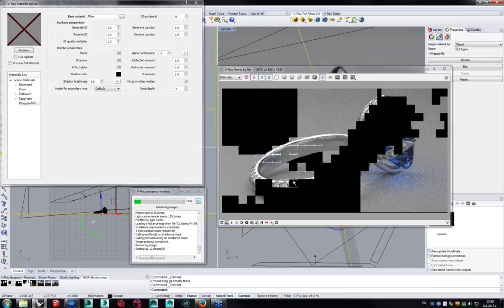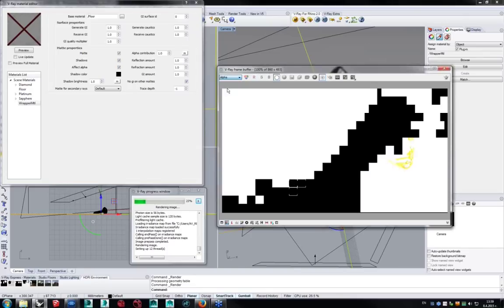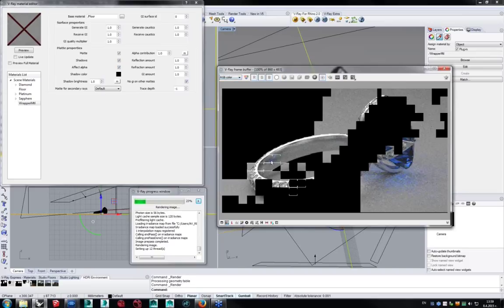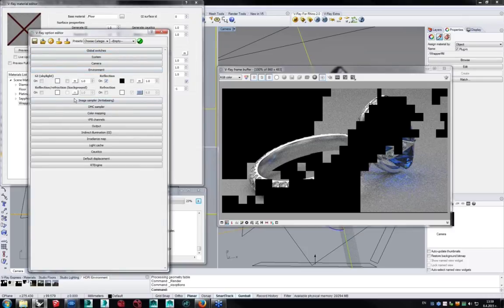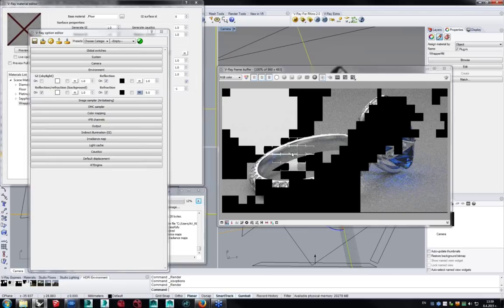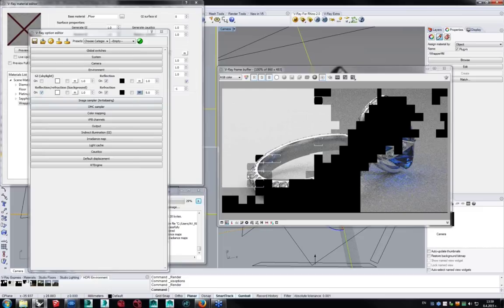So there we go. Now we're not seeing it, but I can make it visible later. Just give me a moment, guys. One thing that you need to do is just apply for the background. So just for the reflection black, for the refraction also black, and I want to have a white background because I want to see how it will look like. There we go. So now currently I'm using the white from the background and I'm removing the floor.